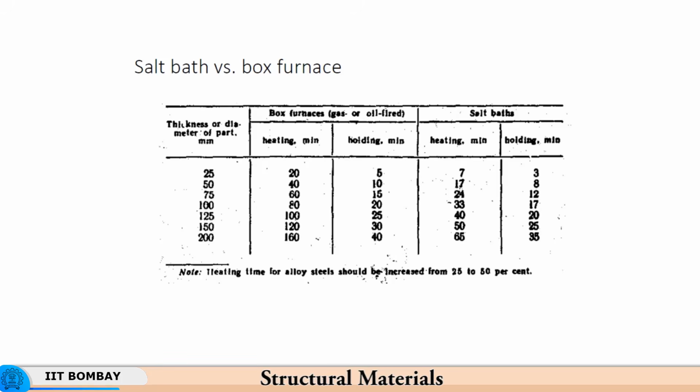Now, these salts have got very high specific heat. So, once heated to their melting temperature, they can be held at that temperature without any difficulty for long durations of time. So, the temperature control with salt baths is much better than box furnaces, be it gas fired or oil fired furnaces.